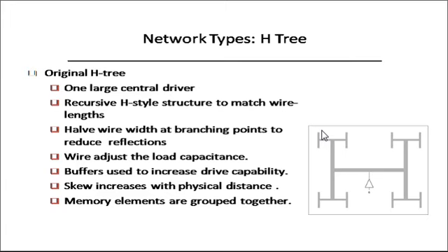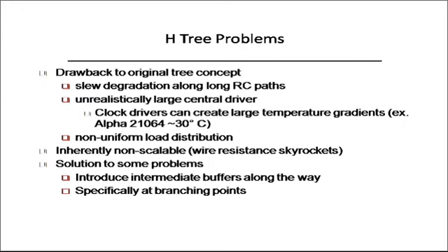If physical distance is more, the skew may increase, but this technique is going to have a physical design in such a way that the clock will reach all the flip-flops simultaneously. Hence, it tries to reduce the skew as low as possible. This is the H tree type structure. Now we will see what are the problems associated with this also.